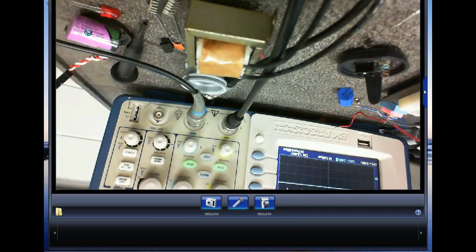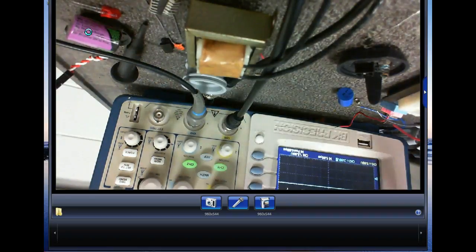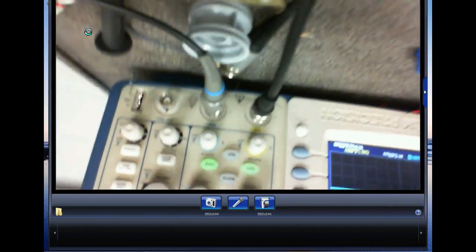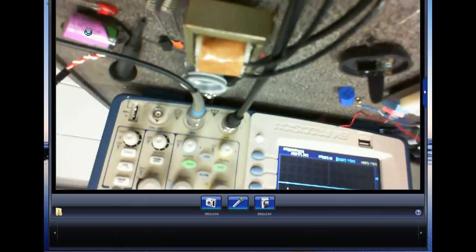The biggest problem we have is they generate tons of electrical noise. When these turn on, we're loading our input power. When they turn off, we're not loading our input power. So they generate a lot of line noise, and they screw up the power factor of the system. So there's a little more to it. They have to really, really filter the input, so a good one will come with input filters.